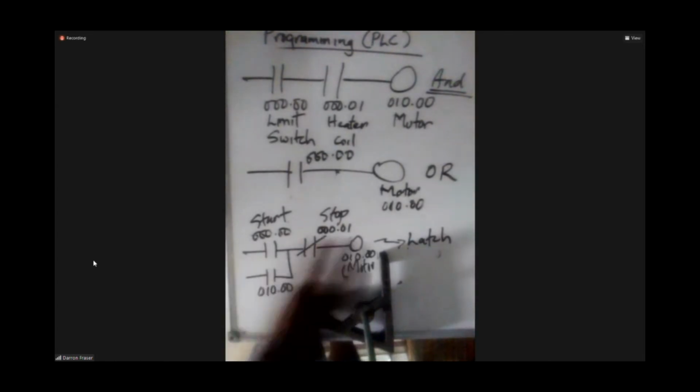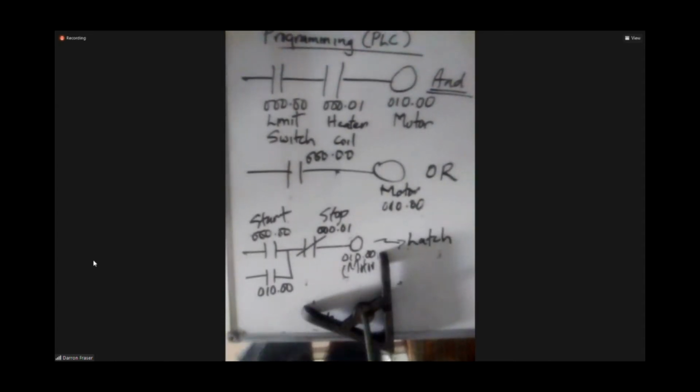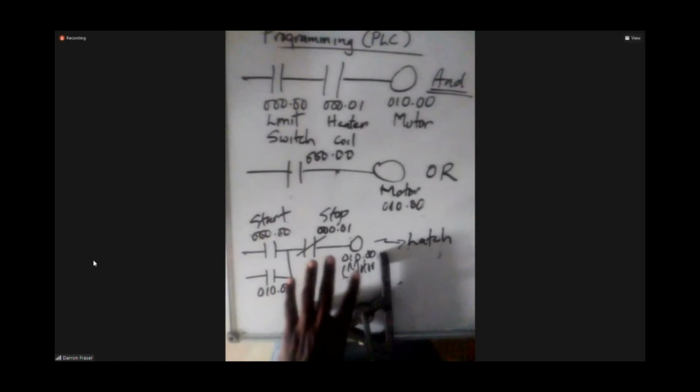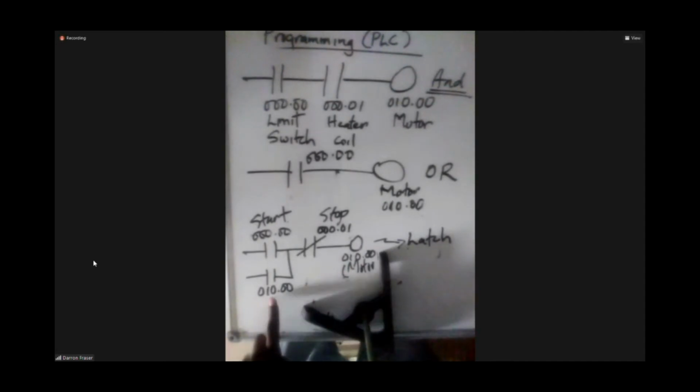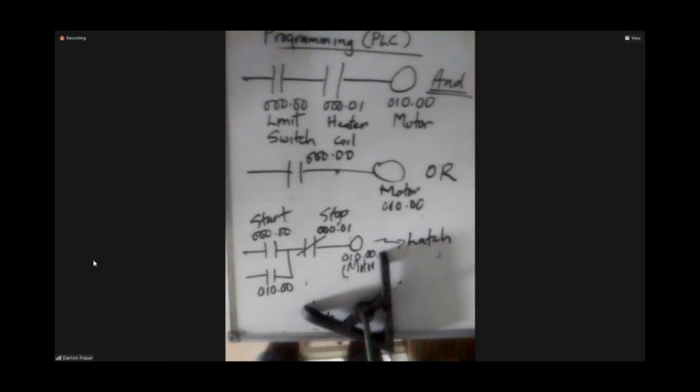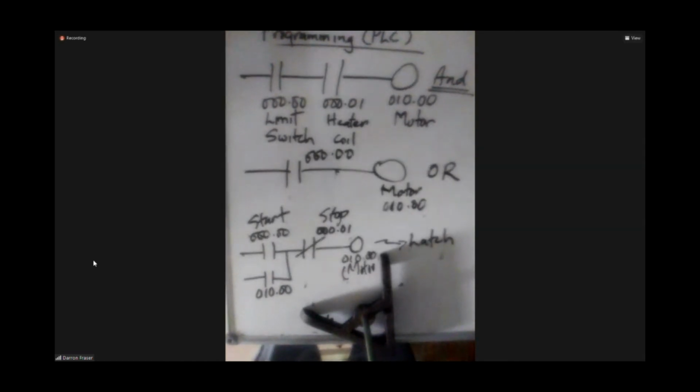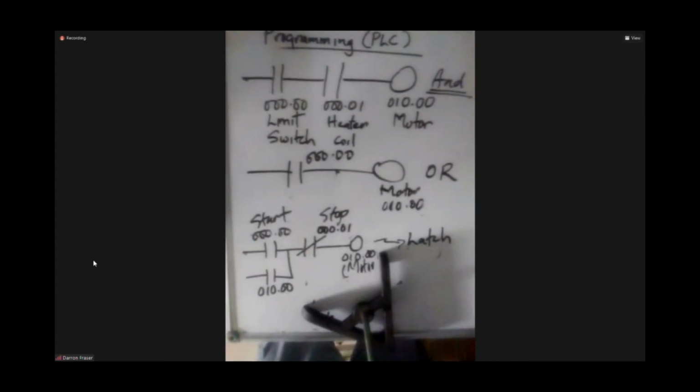This whole latch thing, first of all, any PLC program allows for an output to be regarded as an input. Meaning that you can use the fact that I turn on the motor and use the fact that the motor is on. Because now the program stores a bit in the memory of the processor.